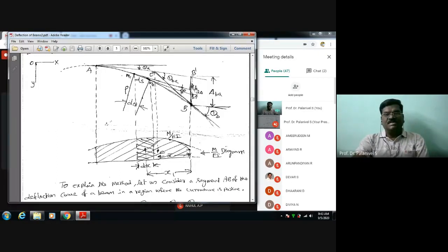Now, what is this P1 P2, or d del? We are making another assumption: the deflection profile of the curve is almost flat. These two tangents are almost horizontal. That's why we can make a small assumption that this arc, x1 into d theta, is equal to this d del.